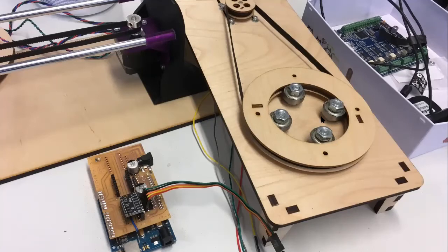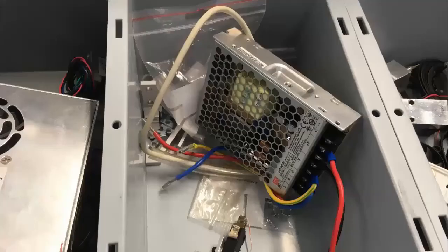You can anyway use a central rod to turn it around, but with a belt drive like this, it's going to make it easier for the motor to turn it. The motor has a certain torque limit, so if you make it like this, you need less force from the motor in order to turn this, and thus you can support heavier objects here, for example.